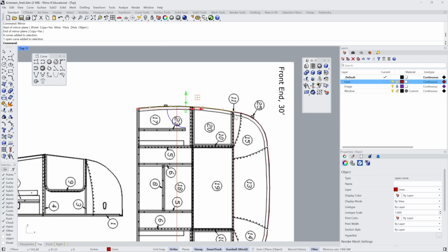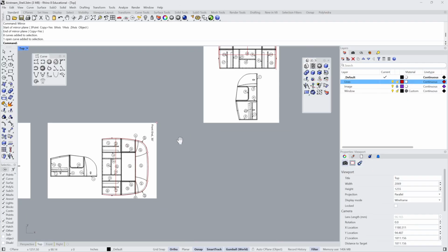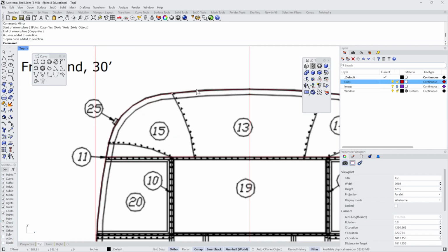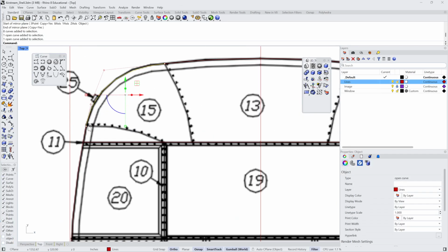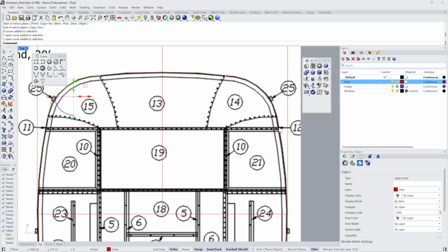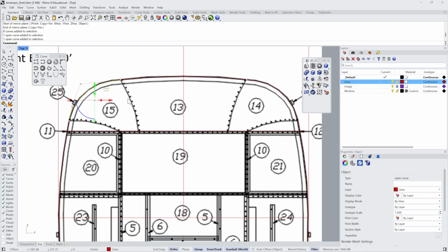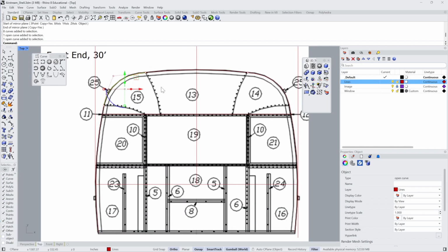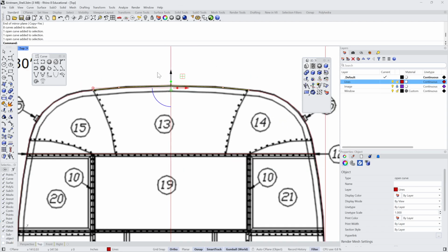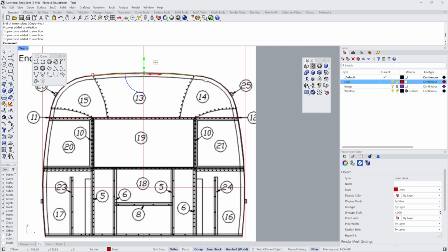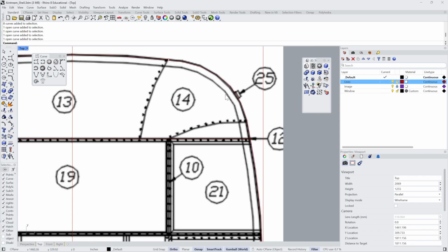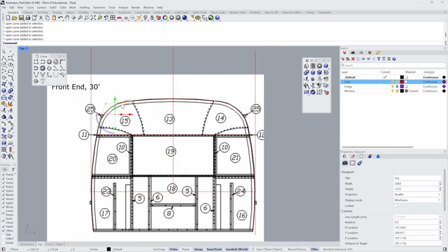And so now I want to come here, and I want to trace these lines, trace this thing. So I've rotated. I just want to show you how I set this up. I originally tried following all of the seams, or breaking up my curves with all of the seams here. That ended up not being the best approach. So I would say what worked well was to identify where the top of the whole Airstream coincides with a panel and maintain that. And then maybe draw the rest of the sides as a single curve, or you can draw it however you want, and then you can join these curves and rebuild them to be one curve.